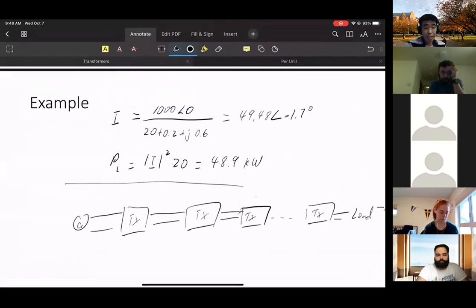And if it's really just a long chain like this, fine, you can keep referring things. But what happens is you have branch connections, going through different numbers of transformers. The transformers may not have the same power rating or things like this. Then in every calculation, what we have to do is take a load, keep referring it to the primary, and do a lot of this sort of reflection to get the circuit correct. There's a lot of work for us.